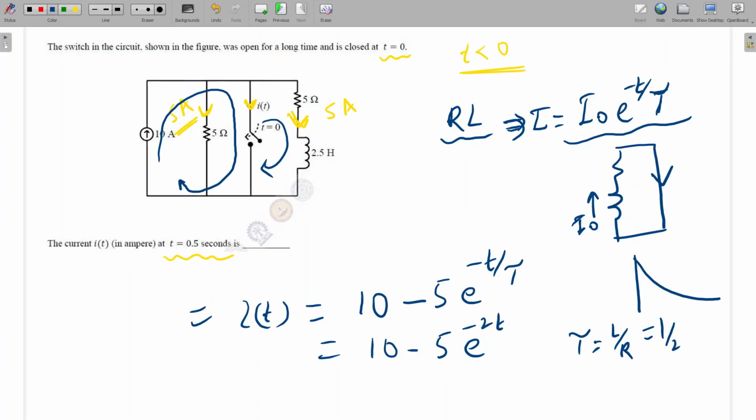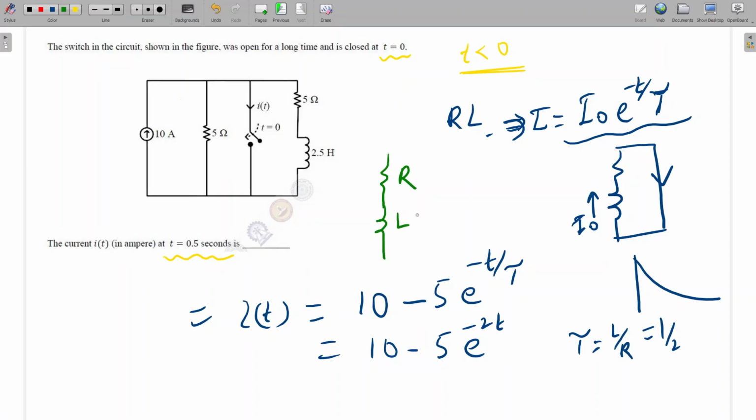Is it clear? I'll explain again. Is it clear to all? Please, can you form this equation by derivation? Yes, that is by derivation only. We can apply Laplace transform, and otherwise we can also apply a differential equation and derive it. If you want, I will derive it now. So see, this is R. L we can write as SL.